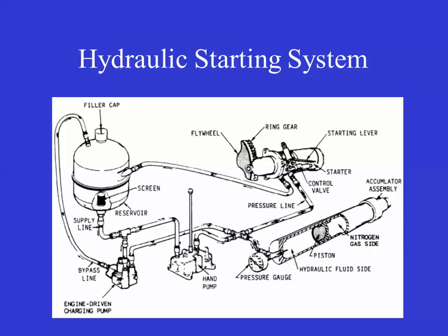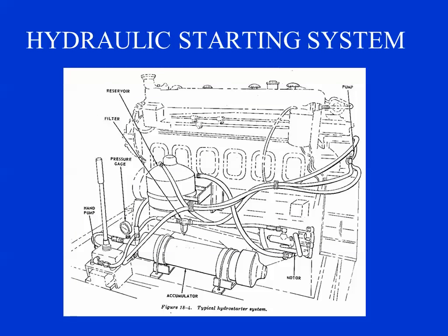It'll drain all your hydraulics spinning the engine, right? And it can't start because it doesn't have air. Then when you come up there, you have to reset the air trip, but you also have to pump up the hydraulics, which takes time. Again, you're familiar with the one on the Bear, so you should have a good idea of how these work.